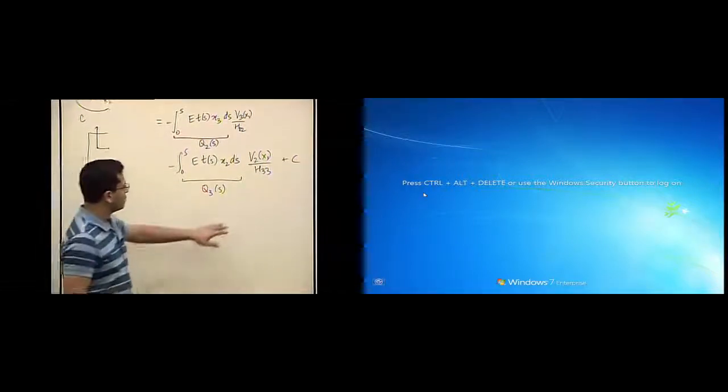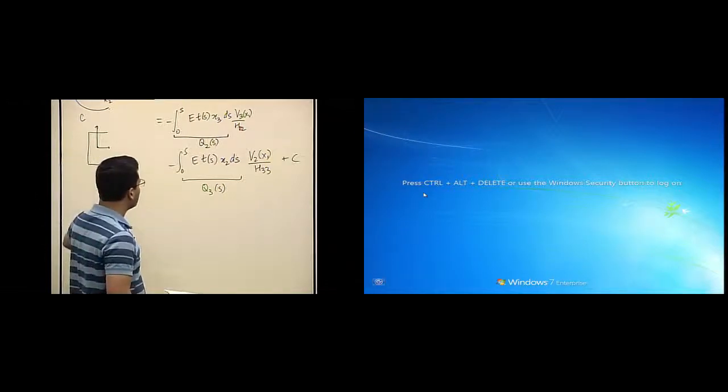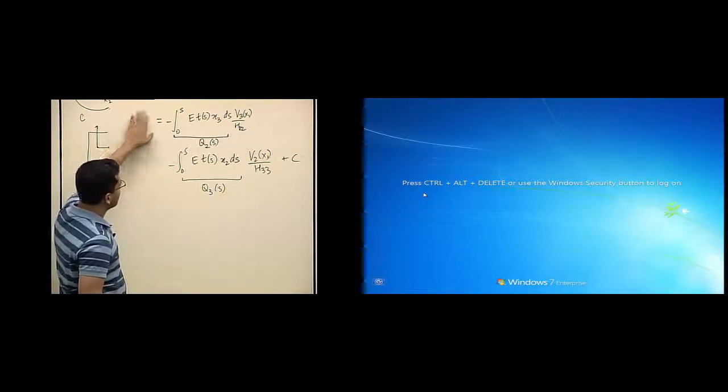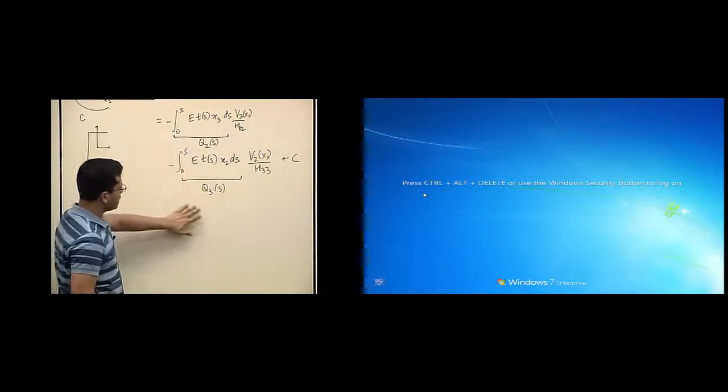Right. So if we have a problem, we can evaluate the bending stiffnesses H22 and H33 by first forcing the frame to be a centroidal frame and then a principal axis bending frame. And then we can also calculate V2 x1 and V3 x1 based on the loads on the given problem. So if we want to evaluate the shear flows, we need to evaluate the integrals Q2 of S and Q3 of S. If we have these integrals, we can solve the problem and get the shear stresses or the shear flows in a thin walled beam problem.